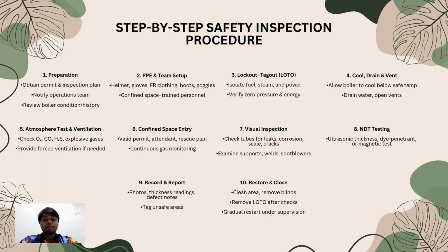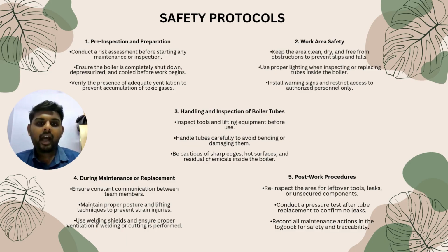Take unsafe areas. 10. Restore and close. Clean area, remove binds. Remove LOTO after checks. Gradual restart under supervision.